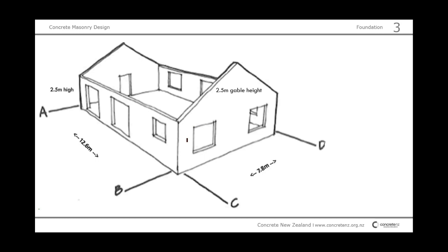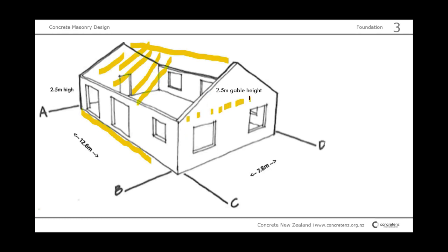So to now design the footing, we have to know what are the loads on the footing. We have two different loads, the one coming from this area. The load we have to consider here is the wall from the blocks, plus the load from the roof, which sits on top here, corrugated metal roof, let's say. On the gable end, however, we only consider the wall, but we also have the gable end here, which we have to add to the 2.50 m wall. 4229 doesn't consider any load from the roof on this wall. There are additional securities also always in the standard, so we don't need to do that.